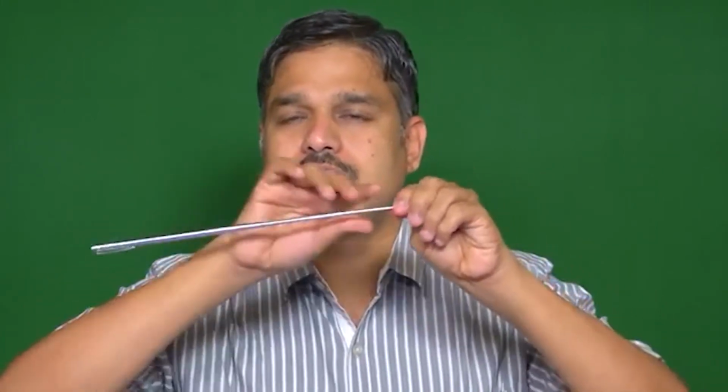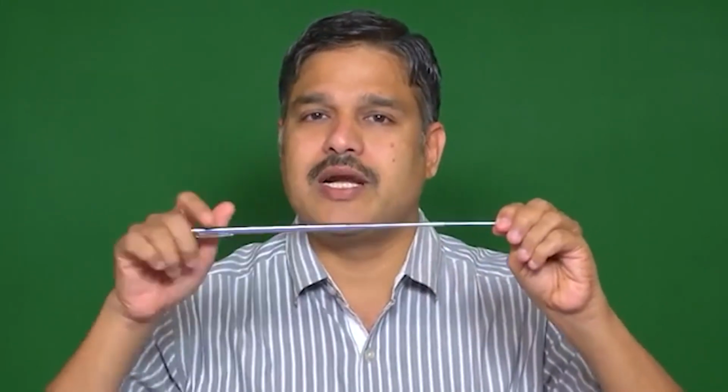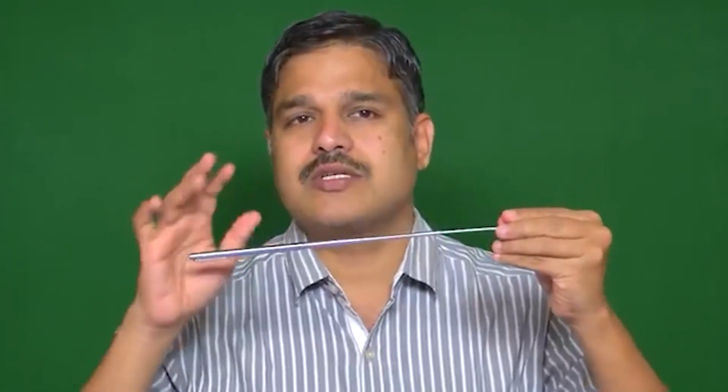The other type of non-structural element is, say, pipelines which are there inside the building. So these two are non-structural elements. In this class we are going to study non-structural elements which are rigid in nature. For example, furniture in the building, water tanks on the rooftop of a building, and electronic equipment placed on tables, all of these come under rigid non-structural elements.